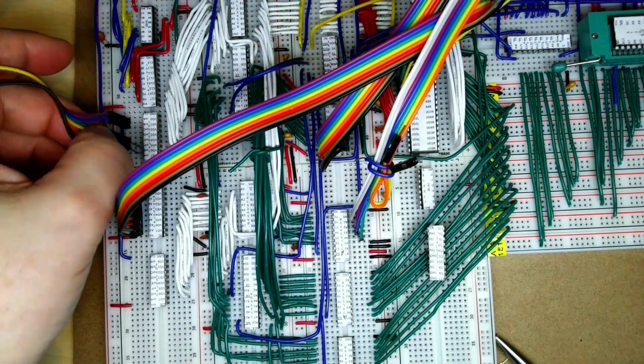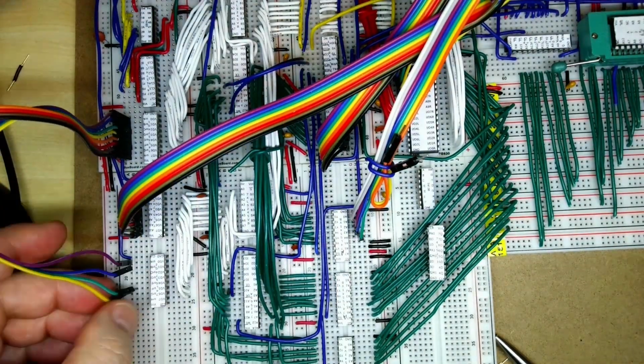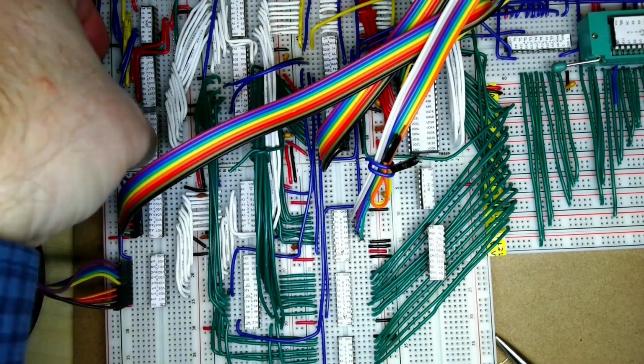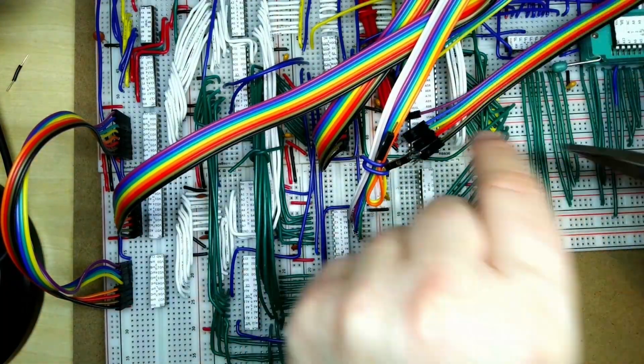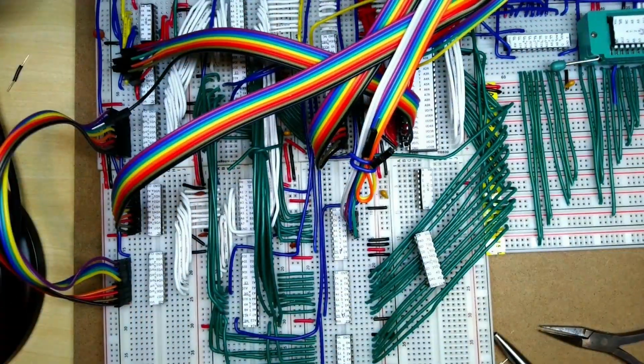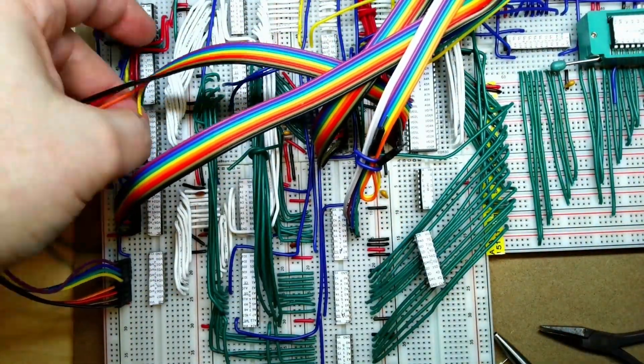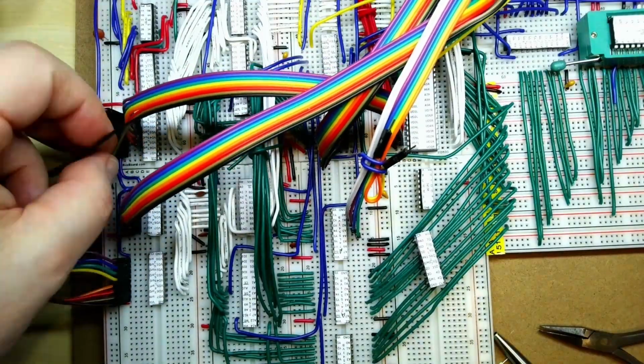Now we want to connect the output of the two graphics latches together, and then we'll be connecting that output to the output of the character generator RAM over there, because those outputs are then also connected into the shift register. So that means that our bit coming out of the video RAM goes straight to the shift register for rasterizing the image.